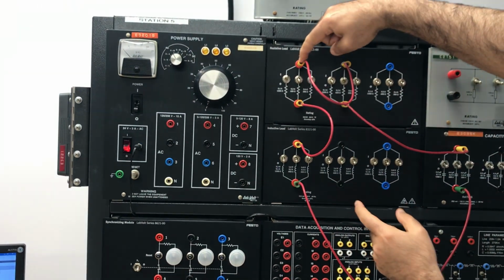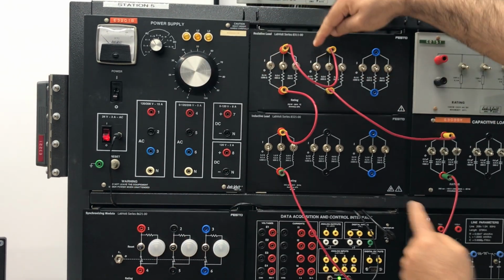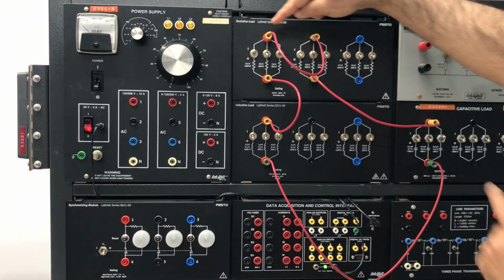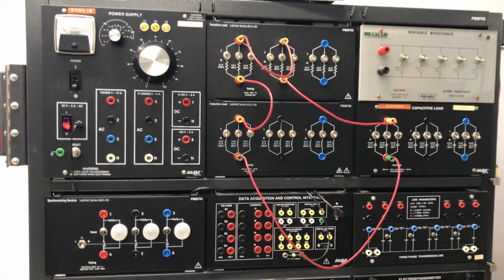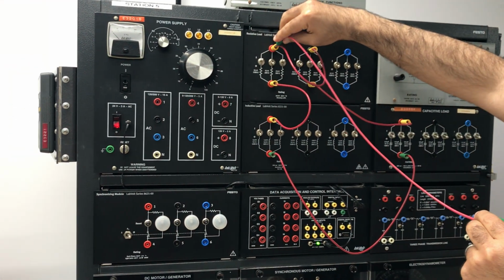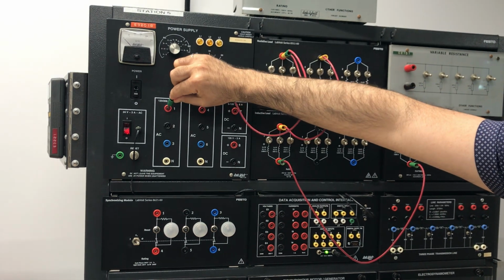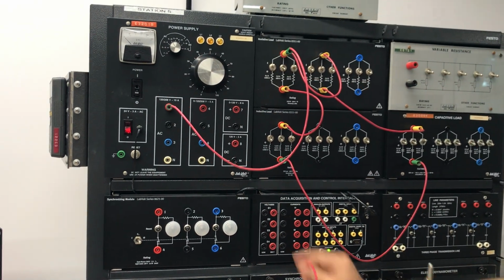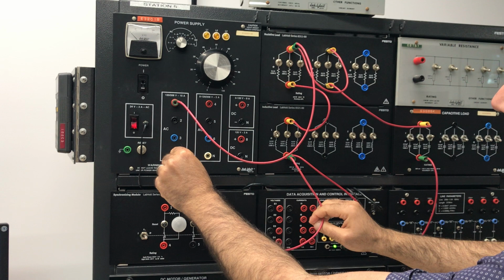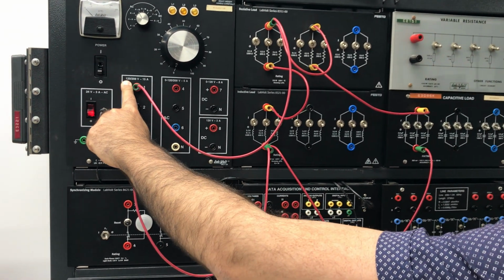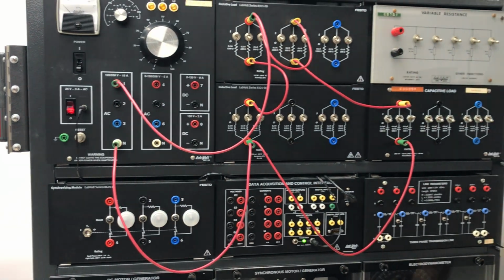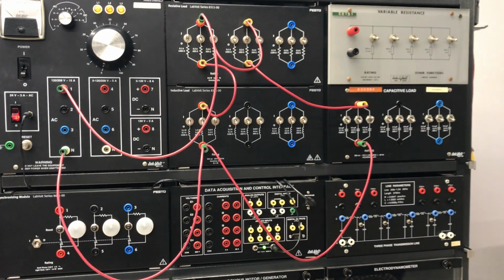And then I will connect this node and this node to the supply, because these two are the same and these two are the same. So I need two wires to connect this one to the supply, and this one to the supply. Again, I'm going to use AC fixed value, which is 120, because the supply is 120. By doing that, I have already connected my circuits.